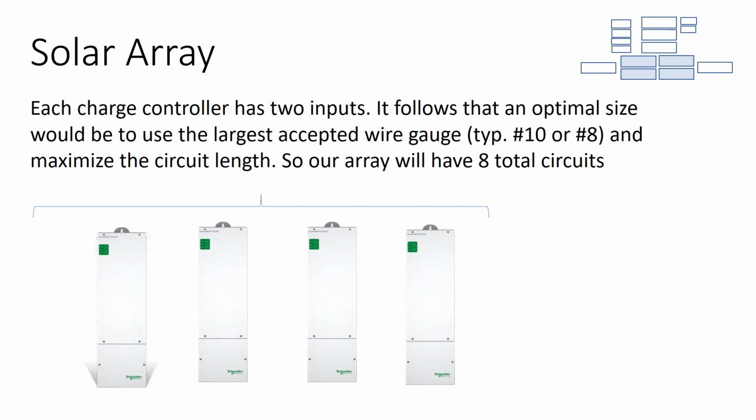Looking at the terminal blocks is another good point where you can spend all this time on wire sizing and calculating the best wire size for your design. A nice starting point is to go and start by looking at the wire terminal blocks on your individual components and seeing what the largest wire size is that they can actually accept.